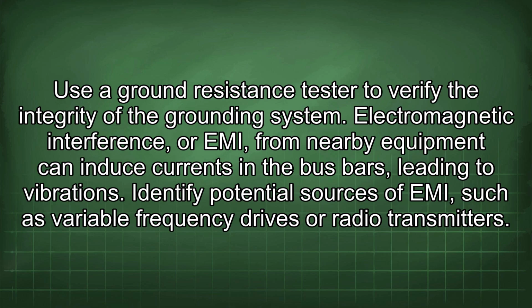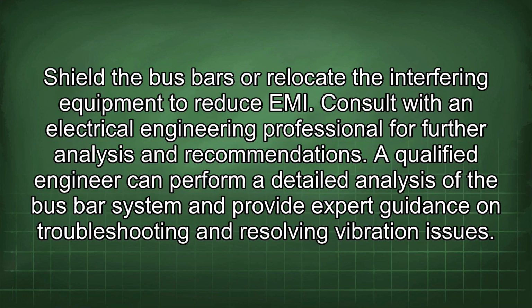Electromagnetic interference, or EMI, from nearby equipment can induce currents in the bus bars, leading to vibrations. Identify potential sources of EMI, such as variable frequency drives or radio transmitters. Shield the bus bars or relocate the interfering equipment to reduce EMI.